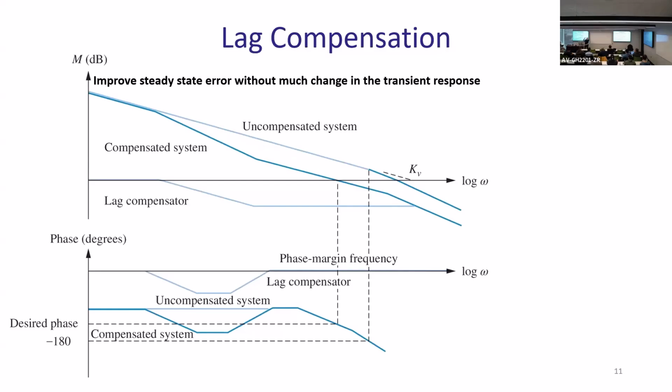So you're looking on that Bode plot and finding point where it's desired phase margin, okay? And you haven't changed that with controller at all, okay? So you're changing only K, all right? But if you're doing that K, it affects the entire plot of Bode, right? Even lower frequencies. But you care about lower frequencies because you want to generate much better steady state error. So you want that to be as high as possible, okay? But if you're taking that entire plot down, it will not be, okay?